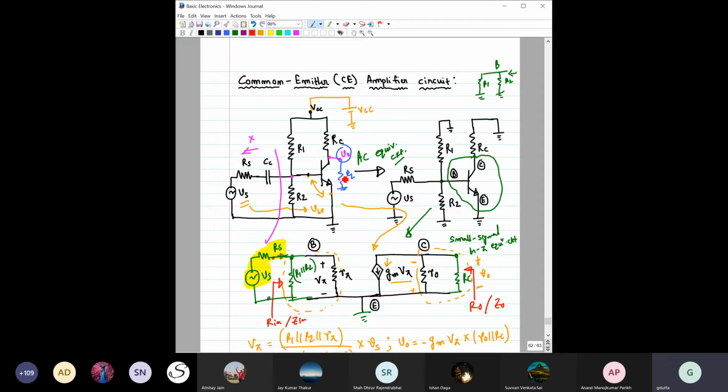If you comment on the stability of this particular circuit, during DC biasing we also mentioned that as we do not have any emitter resistance, there is no feedback loop, no negative feedback. So this circuit is not very stable. If you replace this transistor with another transistor, that is, with a change in beta, this circuit is not very stable, right?